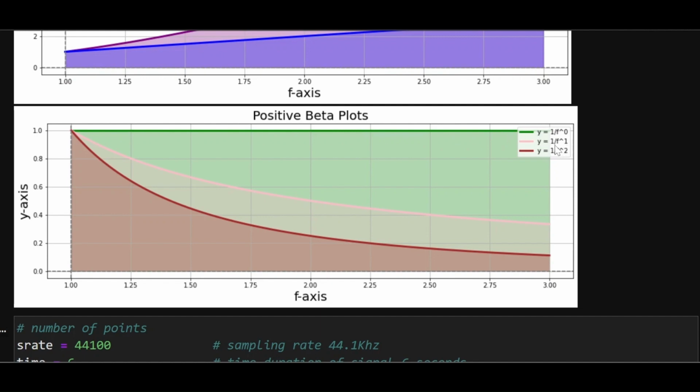So now we are talking about a power spectral density which is inverse of frequency, 1 by f. And this is what is called pink noise. Now it is exact opposite of the blue noise. It is in the other direction. The slope of this curve is 3 dB per decade. And essentially what it is saying is that the higher power of noise is concentrated at lower frequencies, and the higher frequencies have a much lower power component.